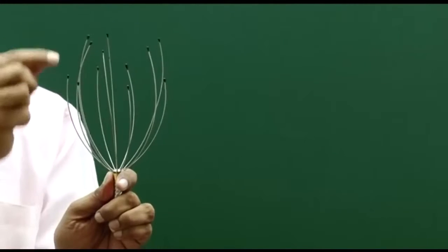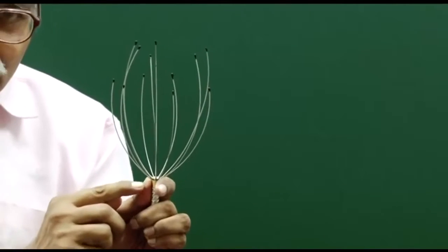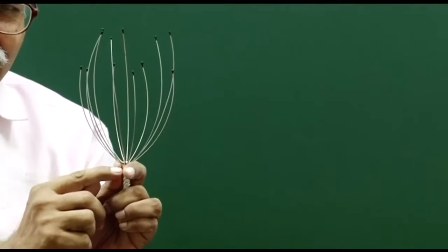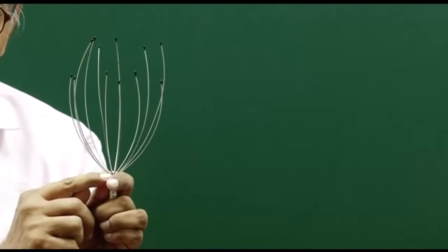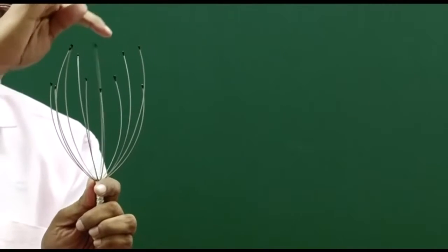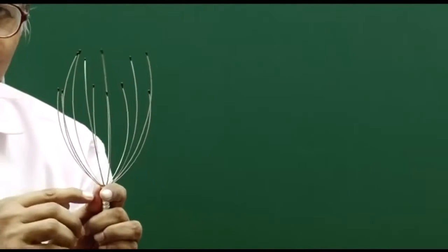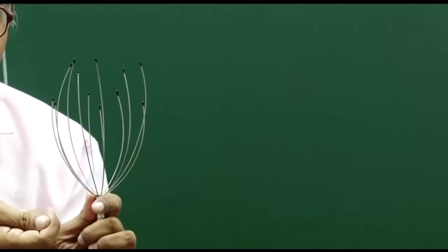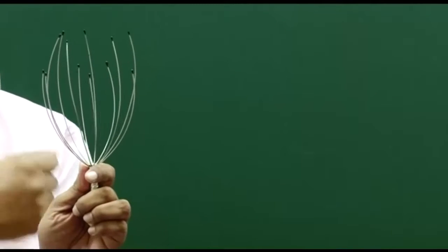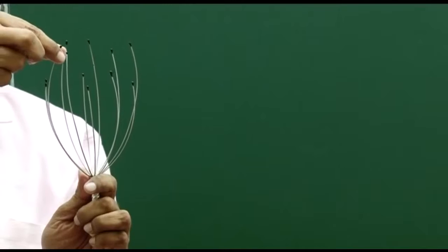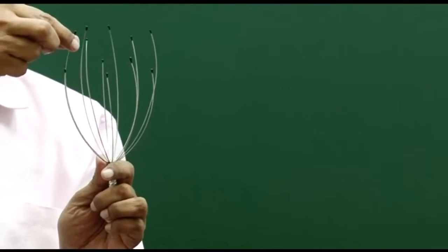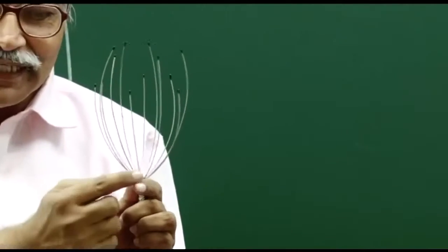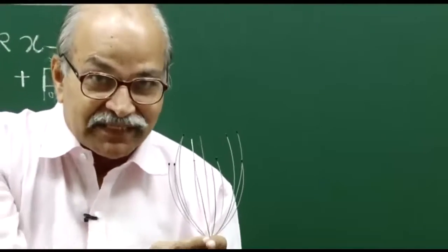The base to which this is attached will also experience some small vibrations or oscillations, some disturbance there. Since all the other rods are connected to the same base, for each of them that base will act as an external source of extra vibrations, because if I am vibrating this, then all others will feel this periodic force through their joints at the base.